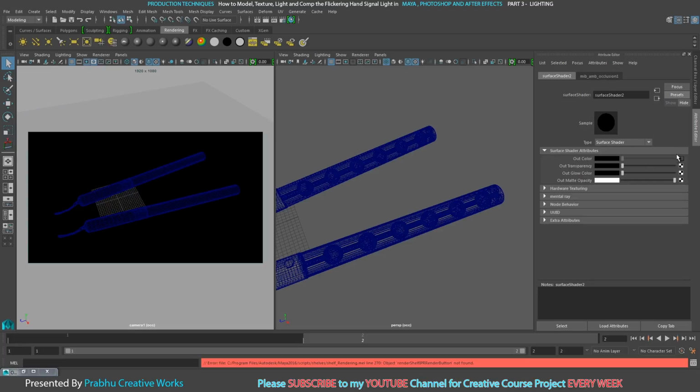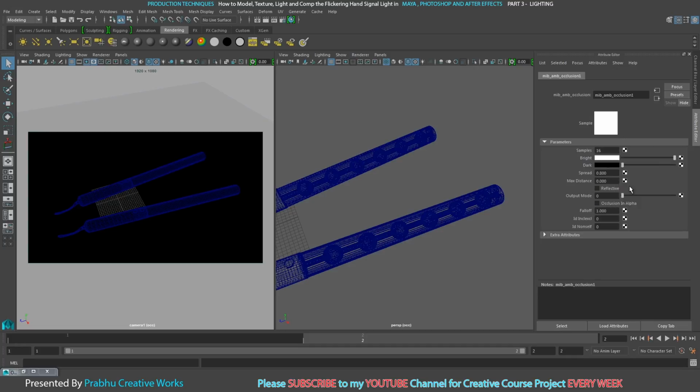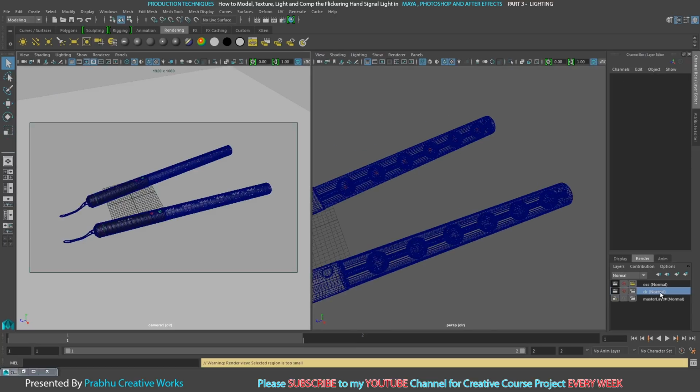So click this out color arrow, and give samples at least 64. In productions they will give up to 128, but it's too high, so our system cannot take that much render. So I will give just 64 and choose maximum distance at least 5. So now I want to set 5 and press enter. Now select the color layer, select the first frame. So select the camera view, hit the render button.